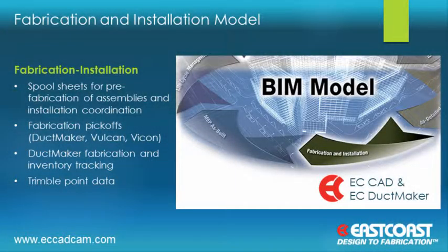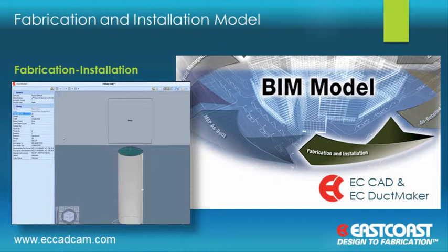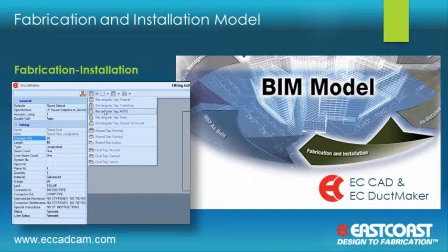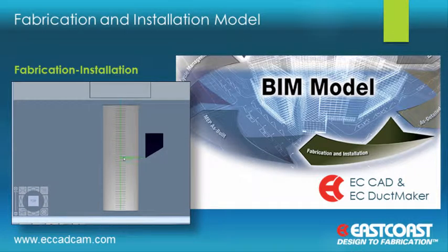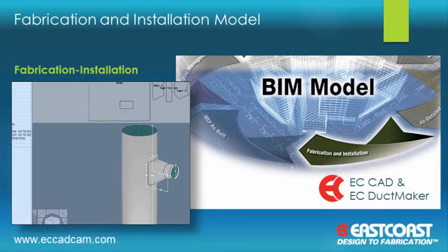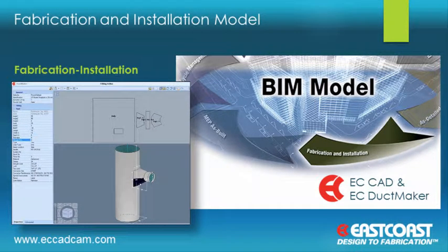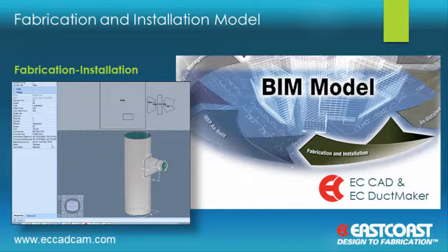To prepare for fabrication and installation, EC CAD provides automated tools for generating pre-assembly spool sheets complete with dimensions and schedules, and creates fabrication pickoffs for use with CAM software such as our own DuctMaker and other interfaces to cutting machines. The workflow for sheet metal is fully integrated with DuctMaker so that the setup for fabrication is performed just once and can be shared by both the CAD team and the fabrication department. The inventory management features in DuctMaker provide piece tracking from the shop to the project, using barcodes to include critical tracking information on each piece.